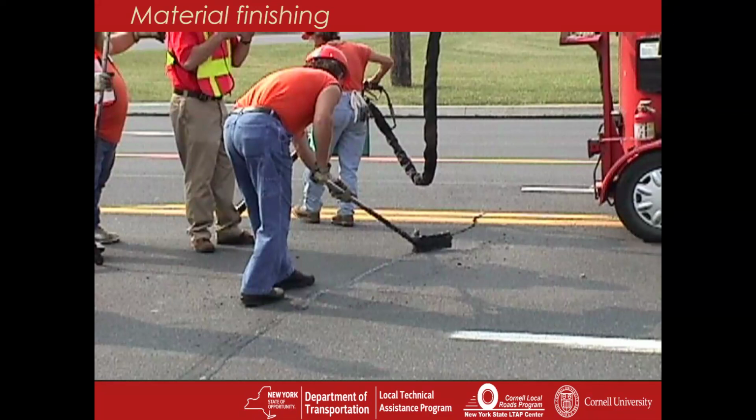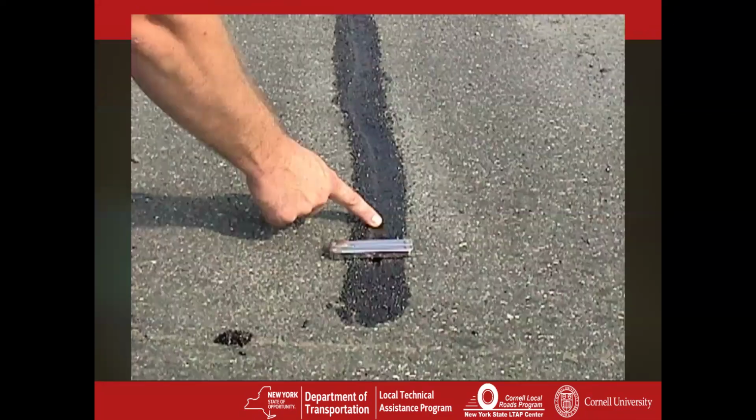In terms of your finishing, there's a real simple way to finish off your crack. Simple is better in this case. Take a squeegee, put an inverted V on the end of it, and you're just running along the top of that newly placed crack sealing material. The next picture will be of what you want to see in the end.